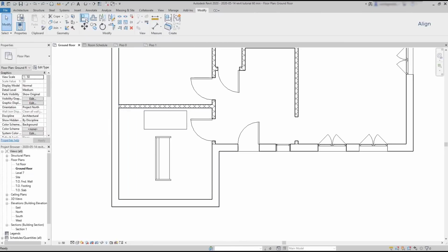So with the Align tool, I do the same process as before, and this selection line is not the one I want, because the sofa would go inside the wall to match the center line. On the options bar, you can see this Prefer, and I can change the part to generate the line of alignment. This time I want it to detect the wall face. Let's try.